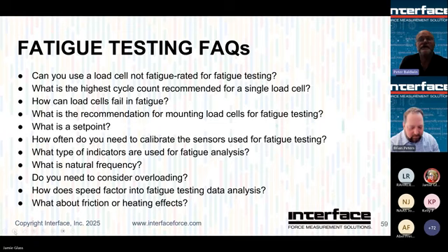We have an installation guide for the 1100, 1200 series, the 1000 series. And so to follow those, as you put down the jam nuts to make sure that it's mounted correctly, and then that it has only the axial loads, and then you can account for or negate any moment loads that might be affecting your test.